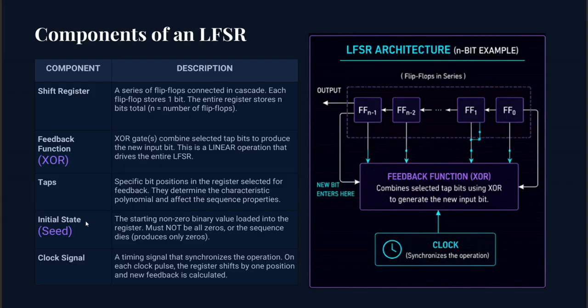Another important concept is the initial state, also called the seed. This is the starting binary value loaded into the register before the operation begins. The seed must never be all zero. If every bit becomes zero, the XOR feedback also remains zero forever, and the sequence permanently dies.